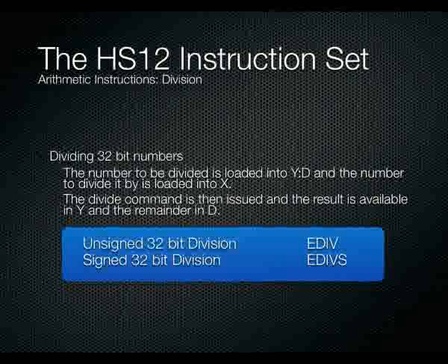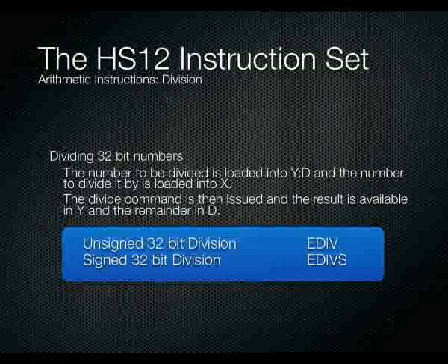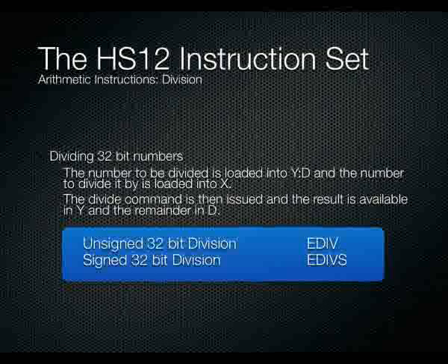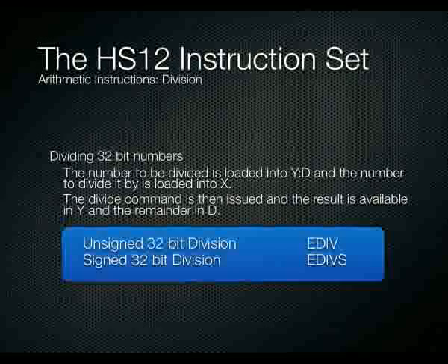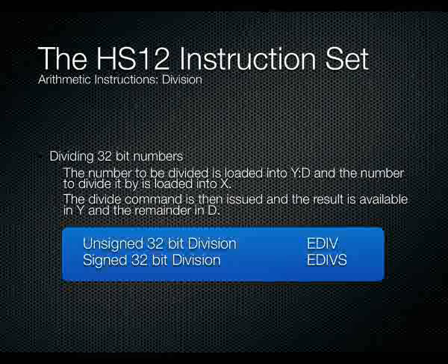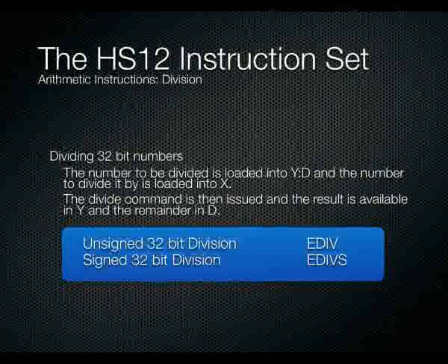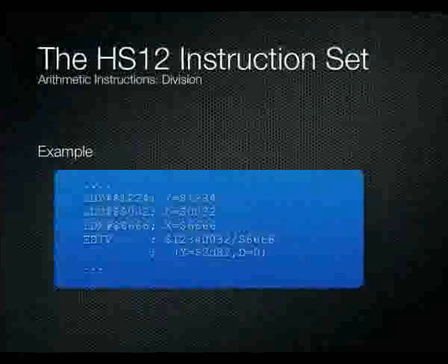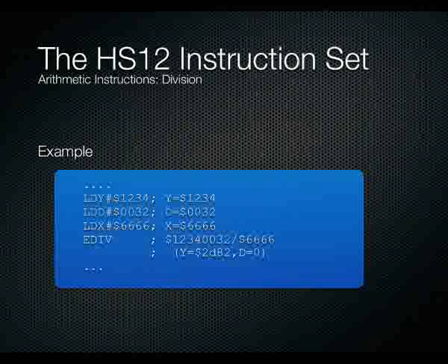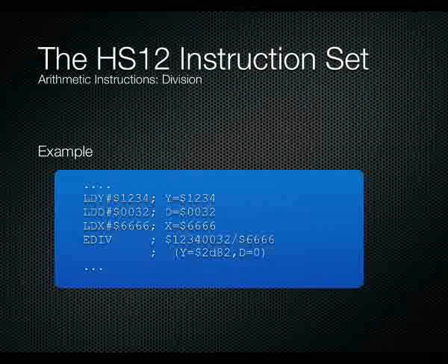the EDIV or EDIVS instruction depending on whether it's signed or unsigned. So if it's signed, we run EDIVS. If it's unsigned, we simply run EDIV. The E stands for extended, because it's not an integer value, it's a 32-bit number, so E stands for extended number. So to give you an example, load accumulator Y with $1234,